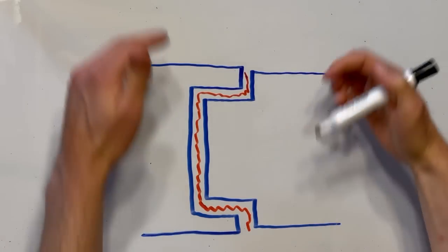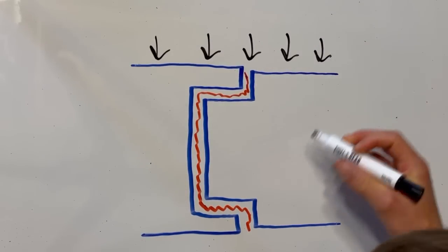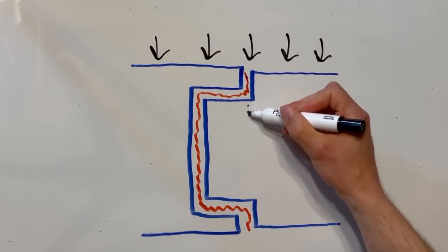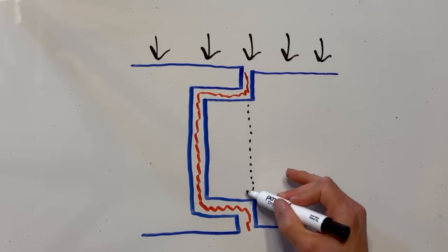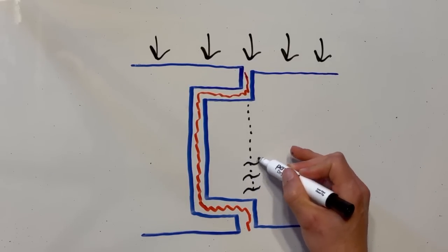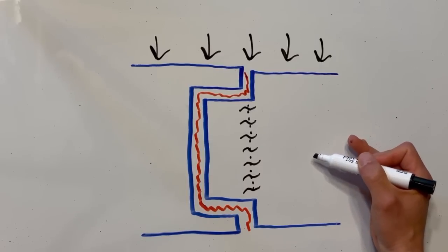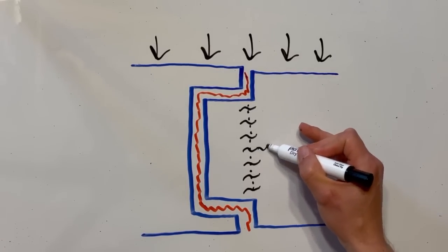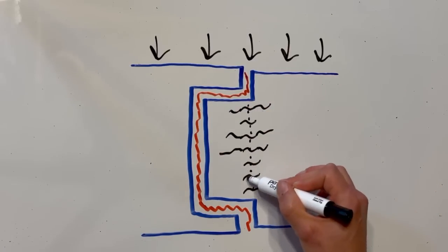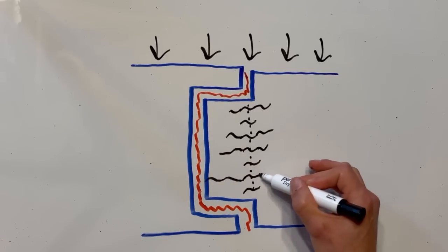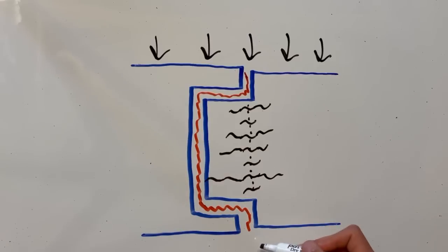So with repeated cycling of that pressure, diving deep and compressing on these and putting shear forces in the composite right there, this very well could start delaminations in between the layers of the composite. And over time, these can grow with each cycle, and eventually they could get big enough where they might propagate into where this adhesive region was.